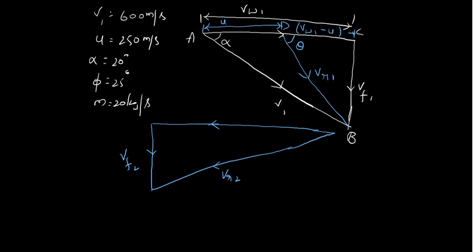I have a little bit of confusion here, so I'll draw the velocity triangle for this relative velocity. I've completed this relative velocity. Now I'll go with the absolute velocity. Absolute velocity is represented as V2. Absolute velocity makes an angle of beta at the exit.